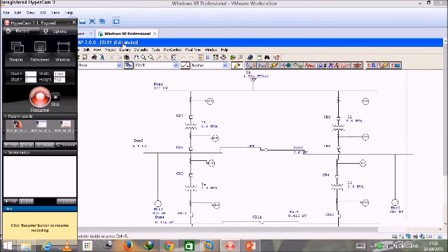Now you can see, as we have designed the whole circuit, this is the feeder, these are the two buses. It is joined by the service transformer. These two are station transformers, these two are service transformers, and we have introduced a few circuit breakers over here, and these are the overcurrent relays. This is the current transformer. This is a motor of 300 horsepower. These are the three buses: bus 1 of 110 kV, bus 2 of 6.6 kV, bus 3 of 0.415 kV, sorry.